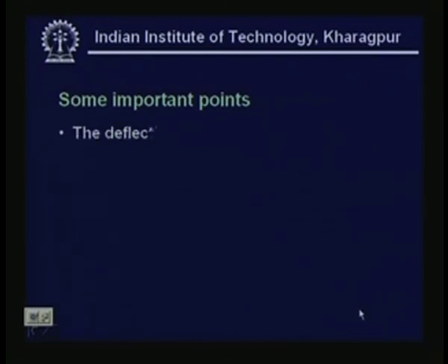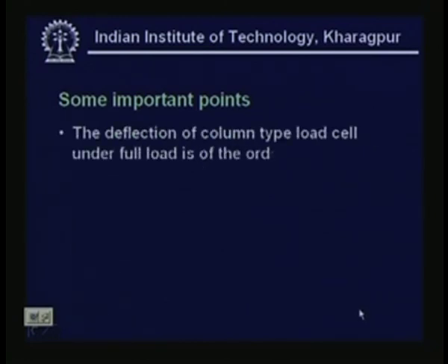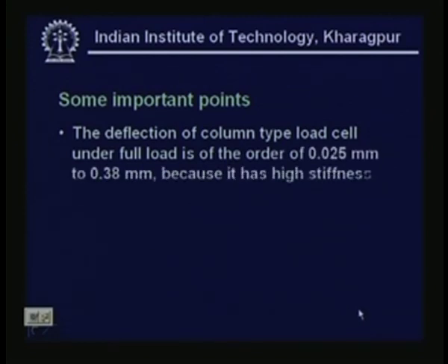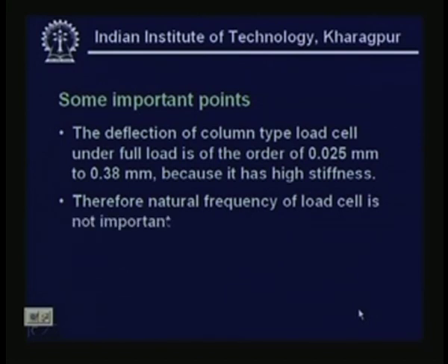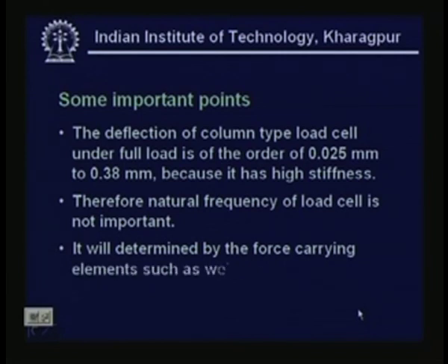Now, some important points. See, the deflection of the column type load cell under full load is of the order of 0.025 millimeter to 0.38 millimeter, extremely small, because it has a high stiffness, and therefore the natural frequency of the load cell is not very important. It will be determined by the force carrying elements such as weighbridges, because the mass of that itself is much higher than the load cell itself. So, the frequency will be determined by that platform itself.